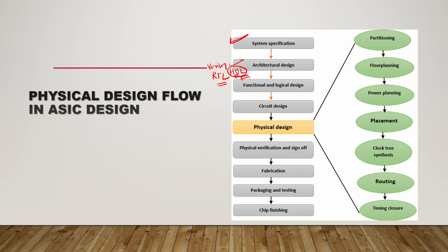After designing, you need to check the circuit and verify it. Suppose a half adder is there. You know the truth table of the half adder, like inputs 0 0 giving sum 0 and carry 0, and so on. You know the truth table, but how will the circuit know? That means we need to go for verification.